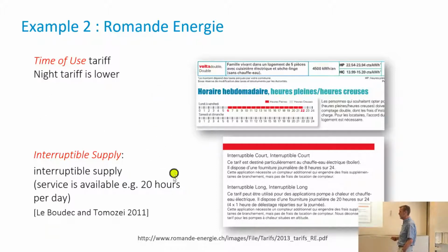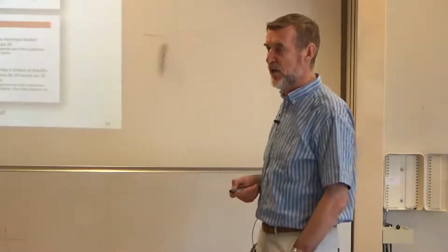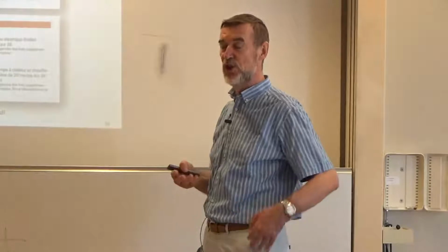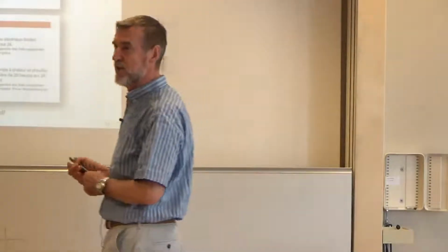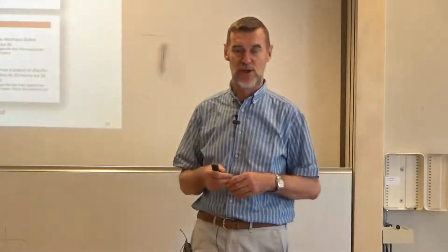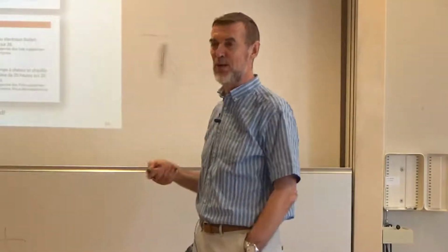Now, when you start having a lot of renewable supply that is non-controllable, like solar energy, the problem is not necessarily exactly to shift consumption from day to night. For example, when there's a lot of solar, the peak generation is around noon. So in Norway, we saw that in their generation system, there is a high price at noon. In countries like now in Switzerland, that's the opposite. In May, June, there is a large production of solar energy around noon, so the prices of electricity drop around noon.